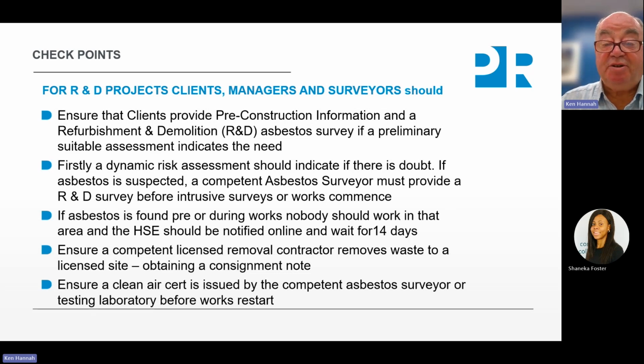So unscrupulous contractors who dump some of it in the countryside or fly tip it somewhere just to avoid paying the licensed site will soon be caught out, because your consignment note can be compared to what was taken away by the contractor. And even then, once it's been taken away, you must have a clean air certificate issued by a competent asbestos surveyor or the testing laboratory before the works can restart.